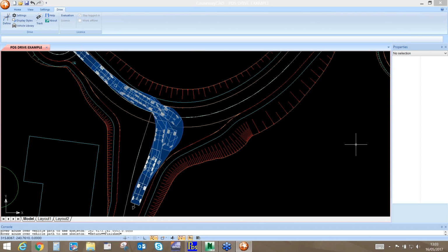Thanks, Mark. Stuart asks, in simulation settings, you have additional storage set at 20 cubes per hectare. He says, I assume that this is like the MAD factor in microdrainage. Is that a default setting? Yes, exactly that. You can set it down to zero. That's fine. It's just we keep that 20 cubes per hectare as per the Wallingford procedure. But yes, you can reduce that down to zero. Thank you, Tom. Question from Scott. Re the annotations, can the run S1 text be removed on the annotations?